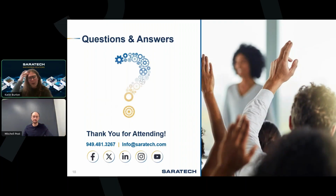Awesome. And then one last question. What else can be done regarding slow solve times, even if your mesh is efficient? So there's several things that you can do. Just a couple that come to mind are you can increase the amount of memory dedicated to a solve. You can enable parallel processing, and you can solve only for the outputs that you need. But always double check everything.